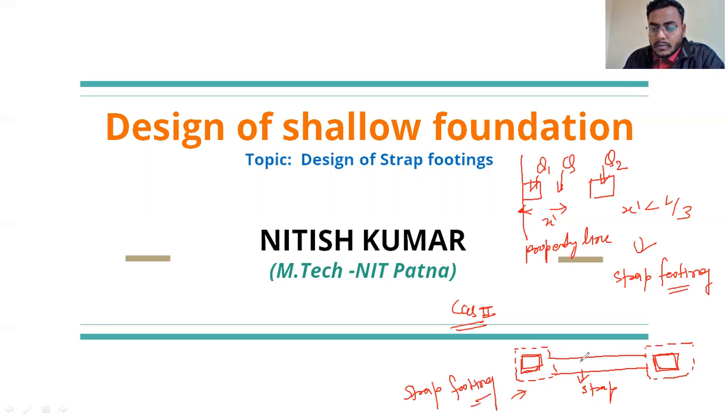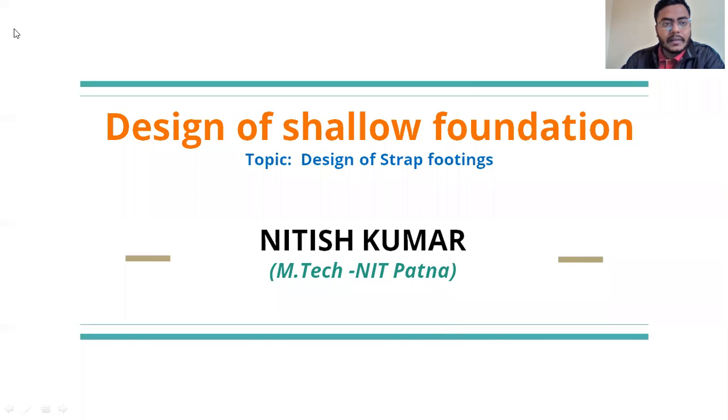This strap does not take any soil reaction. So what is the work of this strap? The strap transfers the bending moment from the exterior footing to the interior footing. So let's discuss the design of the strap footing.